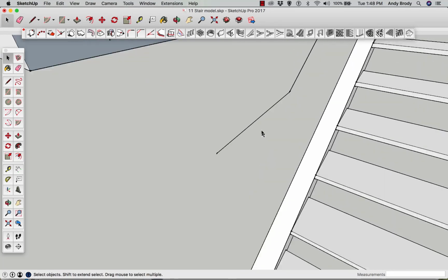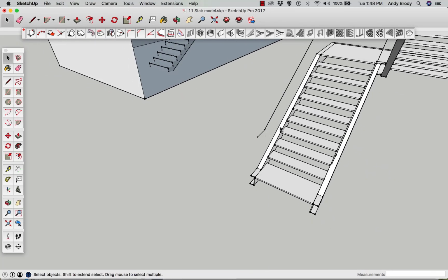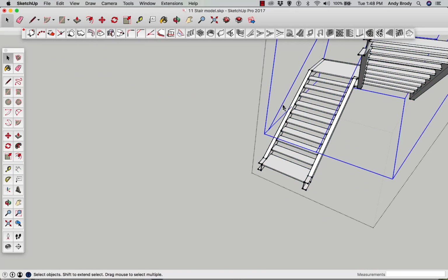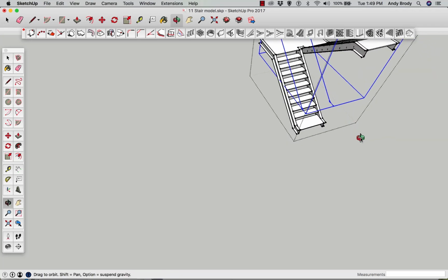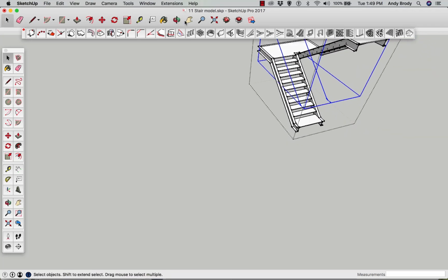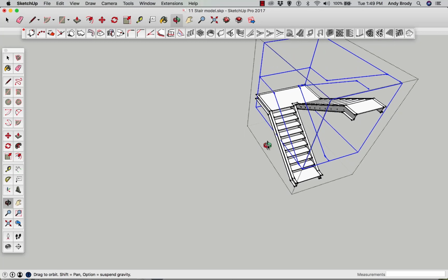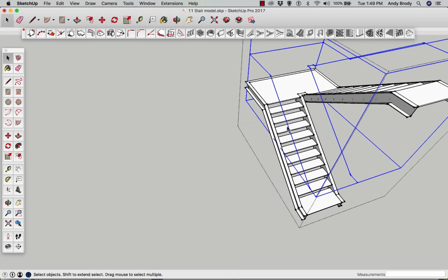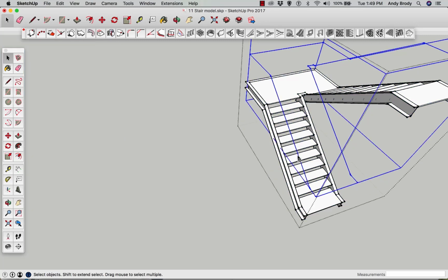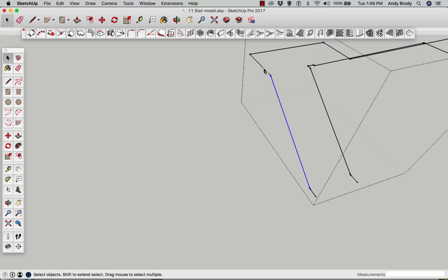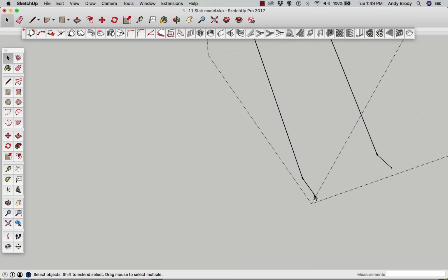So what if I want to put a handrail on these guides that were created here? It's not the easiest thing in the world to do, but what you'll see is it is absolutely possible because 1001 Bit Tools has left these lines in the exact location where the handrails should go. And as you drill down, you'll find that these are individual lines. The trick is going to be getting the circle, that's the profile of the handrail, in the right location.